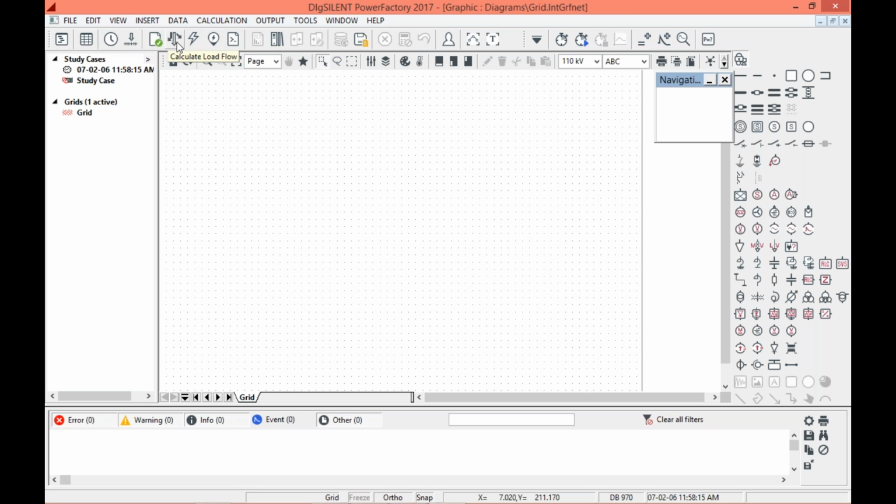If you just want to calculate the load flow, there is this icon. If you want the short circuit, we can click on this. Create the short circuit value, execute script, documentation on script, all these things are in this main menu bar, and this is one more toolbox.